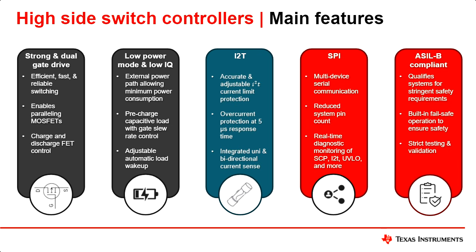Not to mention, this integrated programmable solution and simulation of a melting fuse is also self-resettable, so it can be stored away somewhere where the consumer doesn't have to be able to access the fuse box. On top of the I2T, the controllers, since they are so close to power sources, need to provide fast short circuit protection and uni- and bidirectional current monitoring, especially for DC to DC or power distribution units.